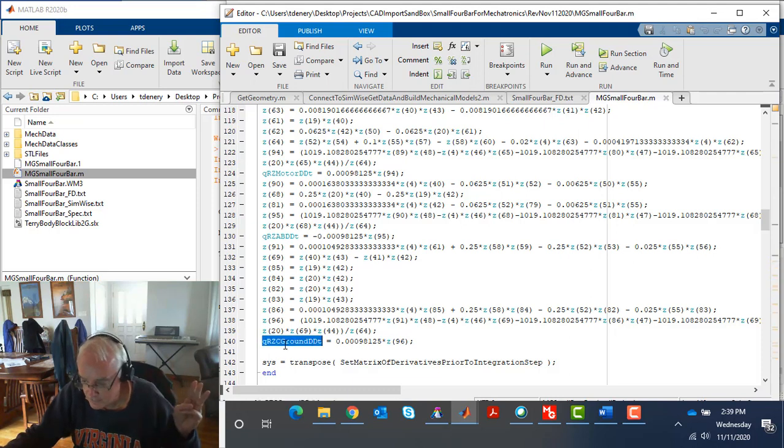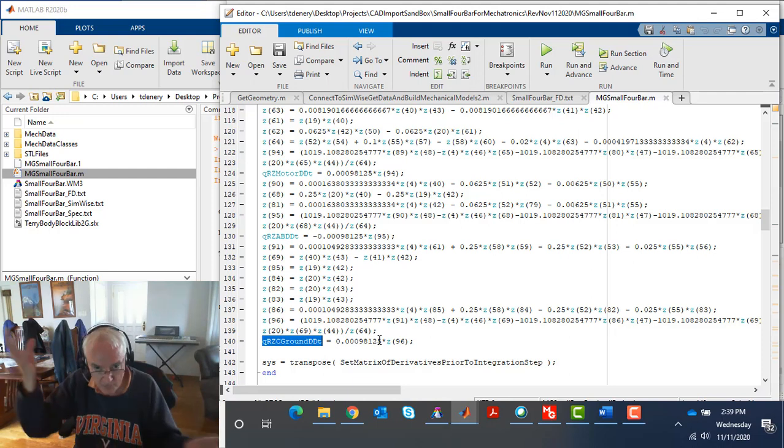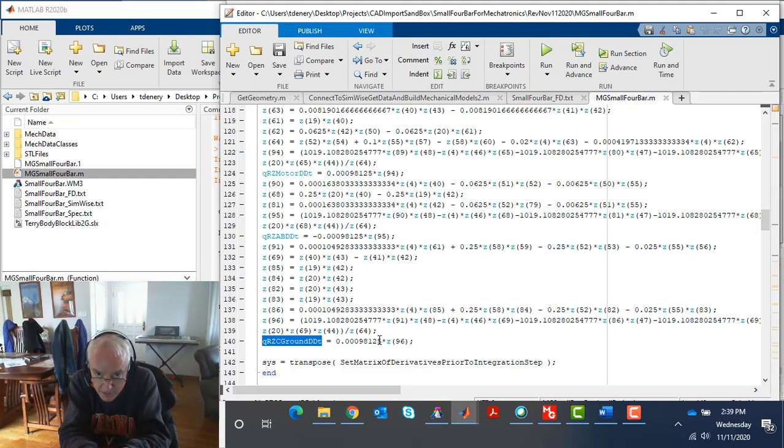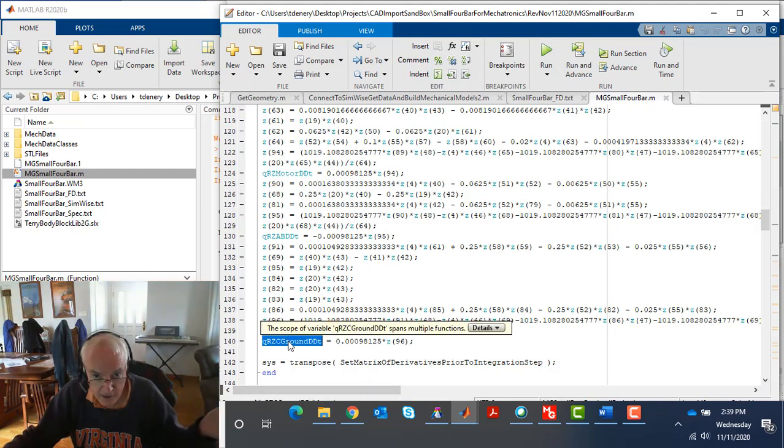The other thing is that in our controller, our feed-forward controller, the job of the system of equations is to calculate the needed torque, right? And here it's somewhat inverted, meaning that we give it torque, and this is going to tell us how it's going to move as described by these second-order derivatives on those 3 variables. So anyways, a lot of mathematics, maybe a lot of stuff that we don't want to be too interested in, but certainly the numerical advantage of reducing this to something that's even more efficient in calculation, I think there's really good reasons to do it.